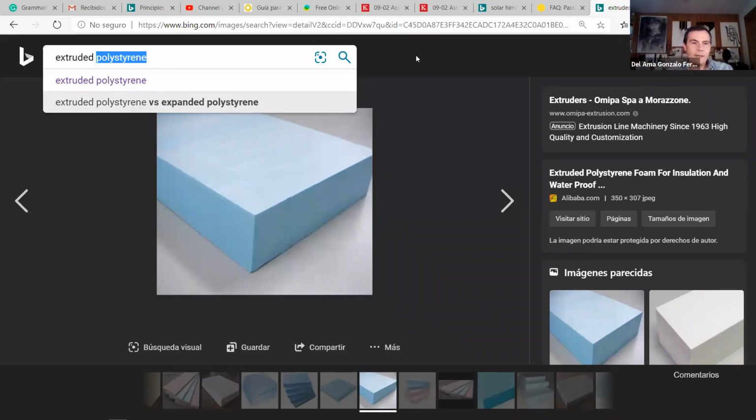But nowadays, things have changed because now we are not looking just at the thermal properties. We are looking at the carbon footprint, how much CO2 we use to manufacture a material. So if we are looking at this, the best material is the cellulose or the wood fiber or the fiberboard. And the worst is the extruded polystyrene. Fiberglass is in the middle. And it takes a lot of energy to manufacture fiberglass. But if you want to protect the structure from fire, fiberglass is the best option.